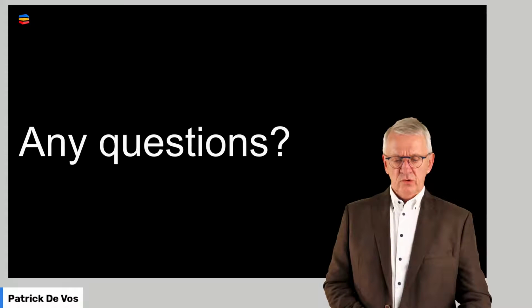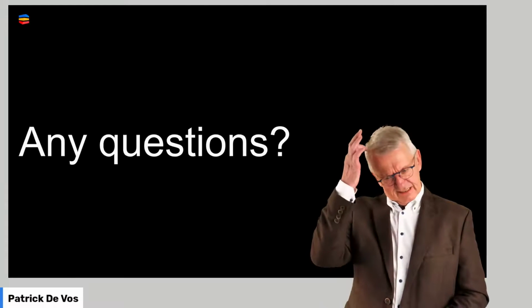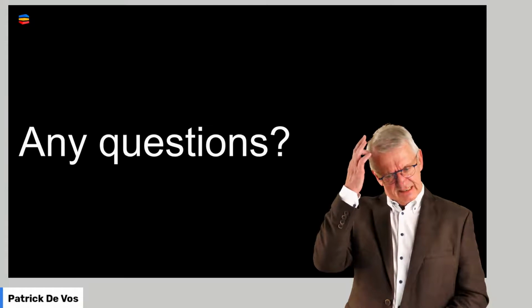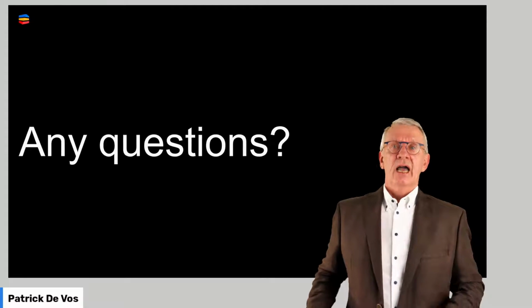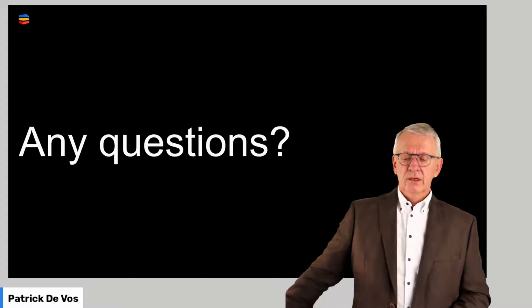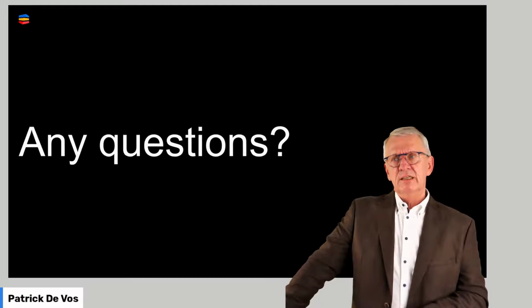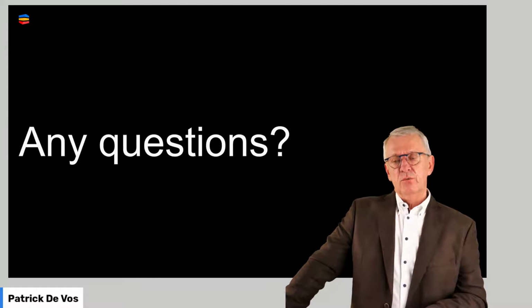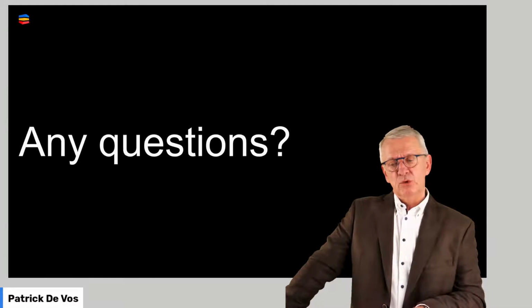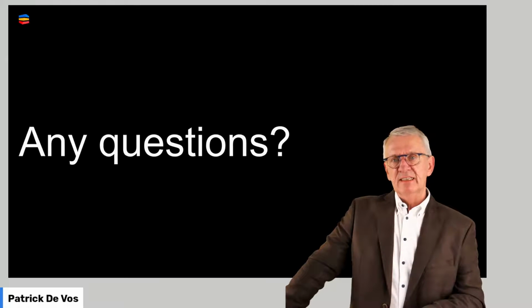I did not talk about point wear. And then the conclusion is, is this not important? It's very important. But point wear is not a wear pattern. If you talk about point wear, it's a wear localization. It's where the wear is appearing.